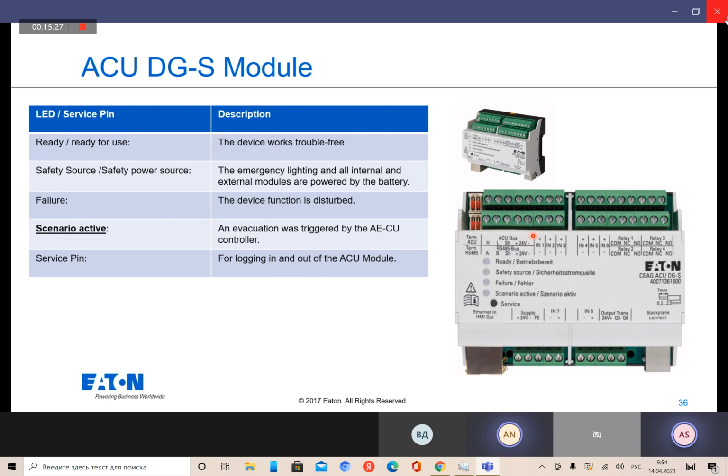But when I talk about this bus here, I will say ACU bus, because it's very important. You will see later why I say that. It is very important that you don't connect anything other than an ACU to this bus. So let's say this is not a CAN communication; let's say this is ACU bus. We have a CAN bus as well. I will talk about it later. But yes, you are right.